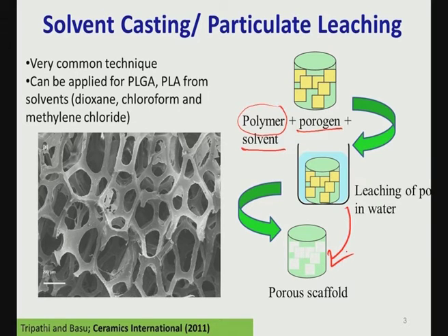This is a typical example of a porous scaffold made of hydroxyapatite. This is from our own research. As you can see, the pores forming here are of different sizes. If you look at the cancellous bone structure, which is highly porous, the pore morphology is also not uniformly identical for all the pores, but there is a distribution of pore size and pore shape in the scaffold, and that is very typical of any biological origin material like cancellous bone, for example.